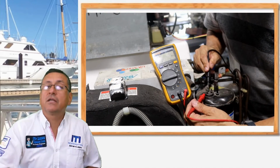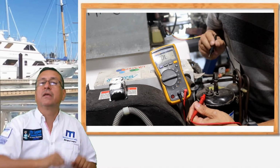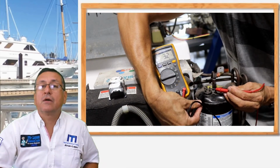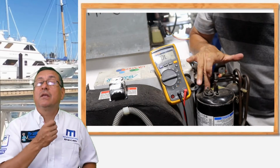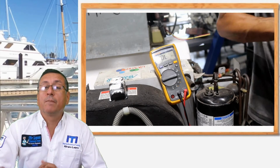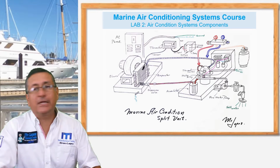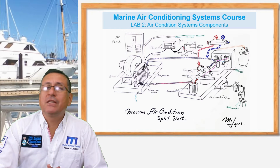And we are going to check the reading in between common and run. 200 ohms. You copy. And after that, we are going to check the reading between star and run. 1000 ohms. Oh, this is good, because the reading in between common and star is equal to the reading in between common and run plus between run and star. This is the verification. Oh no, the equation is not good. The readings are out.